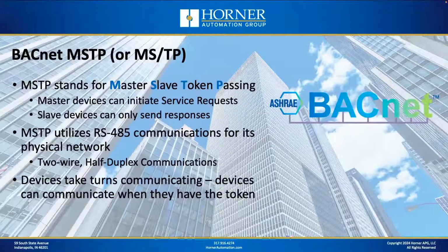Okay, so MSTP, first of all, stands for Master Slave Token Passing. That's what those letters stand for. Always got to have an acronym, right? And as I mentioned previously, MSTP utilizes RS-485 type communications for the physical network for exchanging BACnet data. Now, RS-485 is 2-wire, at least BACnet uses the 2-wire variant, and it's half duplex, which means that only one device can transmit at a time over RS-485.